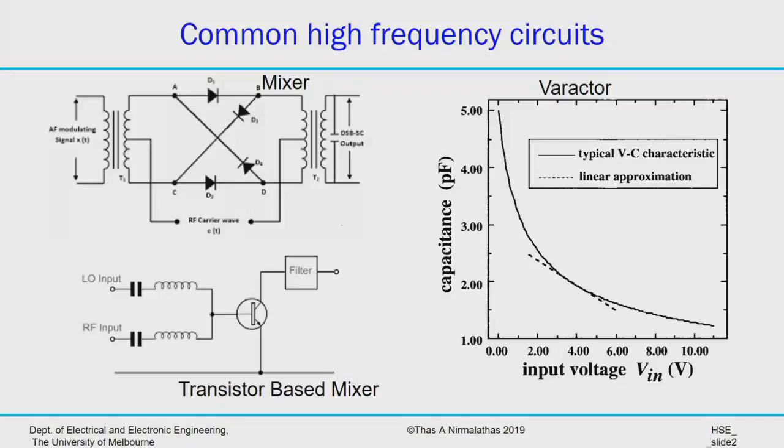And mixers can be realized by different things, but in order to do that frequency translation, the trick is actually the nonlinear characteristics of the device. The most common device is the diode. It has a nonlinear exponential transfer function. We try to operate the diode most of the time where the curve is linear, but it has nonlinear characteristics underneath it.